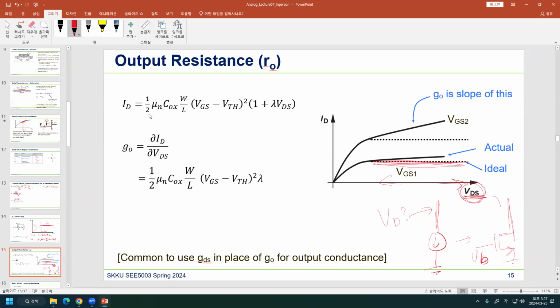The other thing is when we design an amplifier to get a large gain, which is the next common source lecture, we want a large output impedance. If we don't have channel length modulation, that's good because we can have a really high gain amplifier. We're going to get there. But the point here is that we don't want it, but that's the reality, and we have to model it.